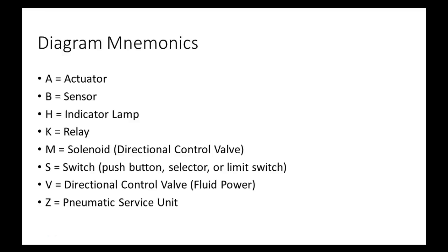If something's designated A, it's a what? Okay, now what's an actuator? It's a unit that turns pressure into motion. So all your cylinders are actuators. All motors are actuators, right? You understand? Solenoids are actuators. So all our actuators are going to be designated A, like 3A, 1A, right? Does that make sense? Then we have B.